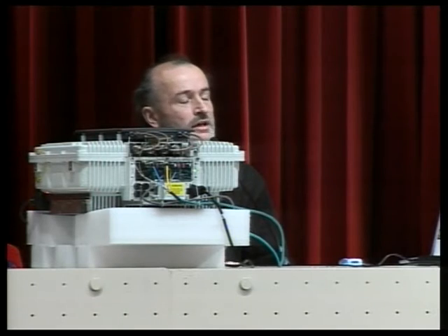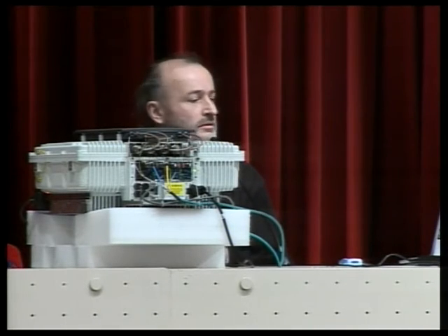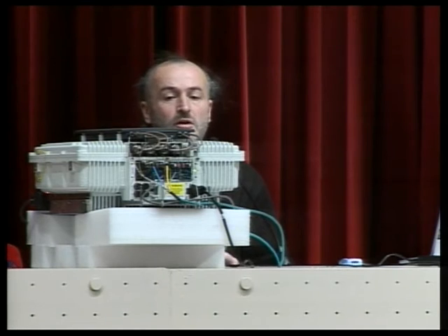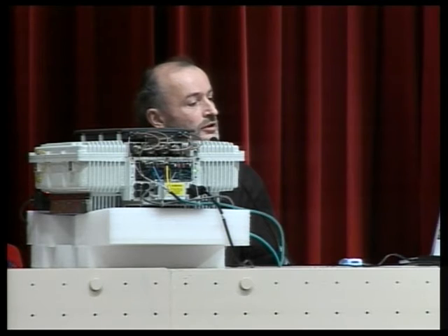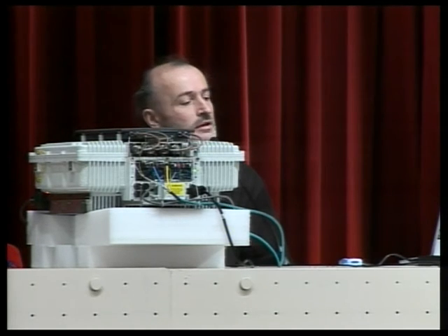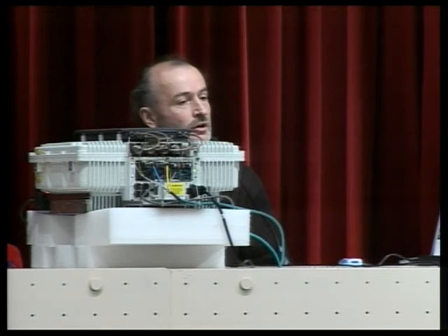But then GSM introduced a specification which clearly defines how this setup procedure works. And our base station, luckily, conforms, let's say, 99% to this specification. So we can look it up and see what we can do with it. This is also a big advantage because in the NDA docs there was no information about how this protocol should work. Basically, an operator who buys such a base station does not need this information. He, of course, buys the software from the same supplier for his base station controller, and so he does not care what's going on the line.